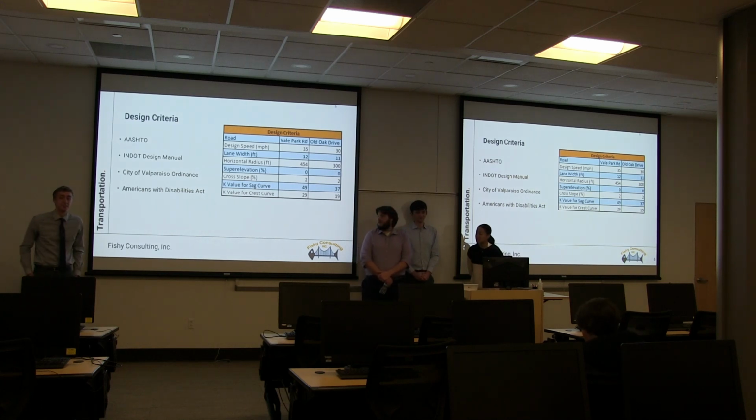Yeah, that's specifically for a vegetated swale, because you want good water quality treatment. Those are the regulations for accomplishing water quality treatment. Well, how about if I'm using a vegetated swale for conveyance? Conveyance is different. The regulations are different for conveyance versus water quality treatment.